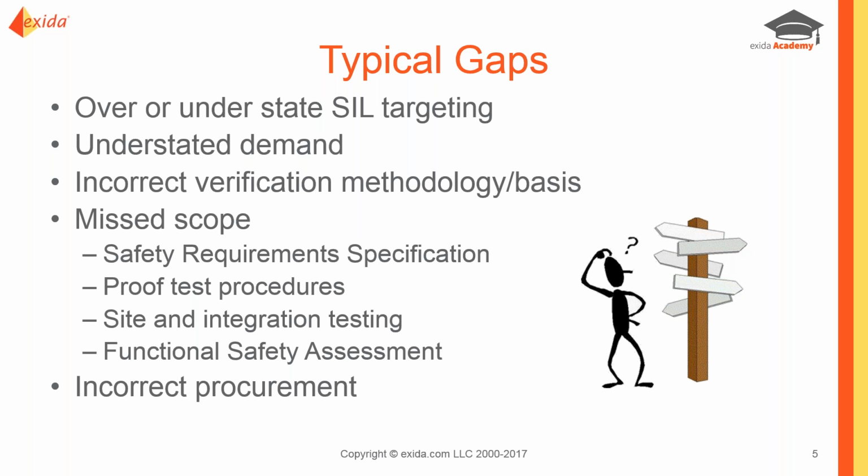Factory acceptance testing for your safety logic solver is something that we typically would find within the quotation from that supplier, but often site acceptance testing and site integration testing with package units is listed as an option, and a lot of times that does not get rolled into the budgets for a project. So again, we get down to commissioning and testing and we don't have those key connectivity tests. And then the standards require us to do functional safety assessments at periods throughout the project.